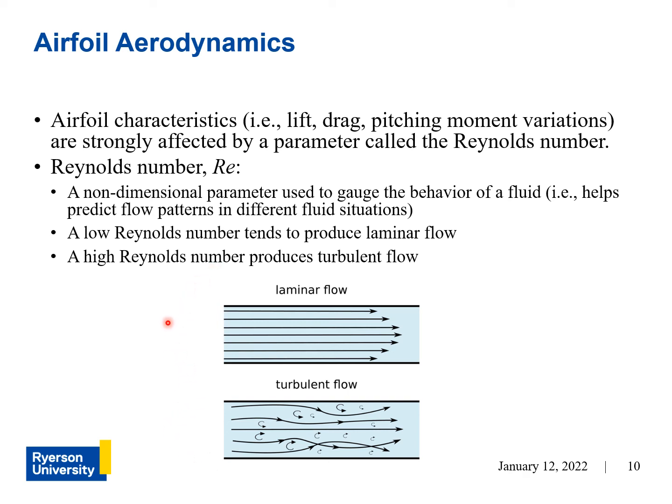Although you shouldn't try to overanalyze the Reynolds number, because it's hard to measure out in the field with what you have. So it's just good to be aware of what that means, why you're given a plot and you see several lines instead of one. It's because that's data obtained at different Reynolds numbers, and that just means data obtained at different flow behaviors.